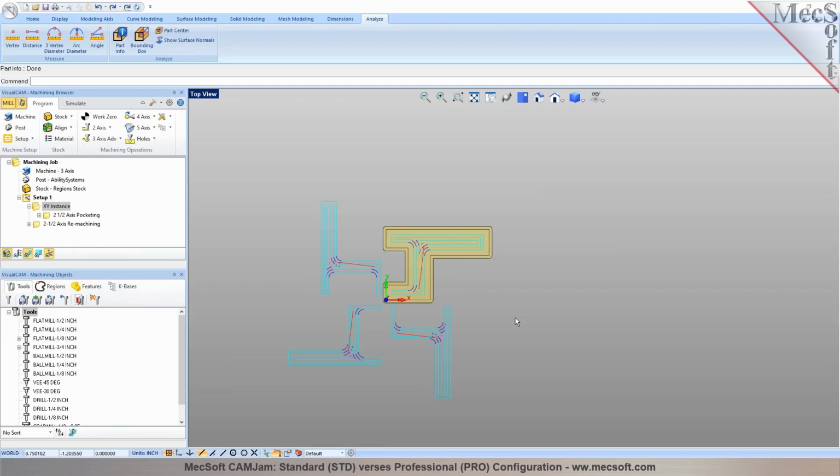I do have a question. I was doing a program where I had to drill and ream 2 holes and then use a grooving tool to create a recess for a snap ring. When I created the grooving tool, I could not get it to drop dead center in the bore. It kept wanting to start from the edge. So basically, I was having an issue with my start point.